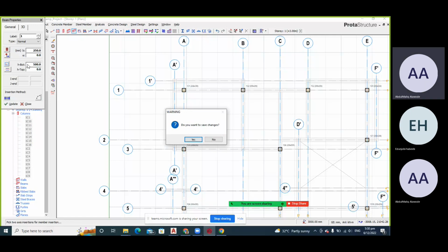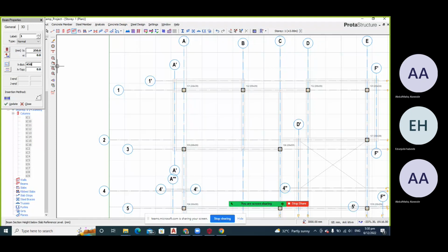There is a table that talks about deflection, a length to depth ratio. So the best size that works with that is 450. In some countries they don't go with 450, they say 500. It's fine, it's not a big deal. But Nigeria is being economical. It's fine with the provision of the code. So we can say 450 by 230.